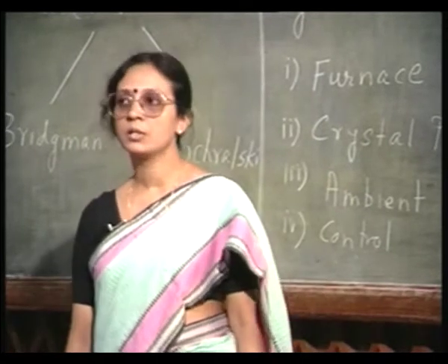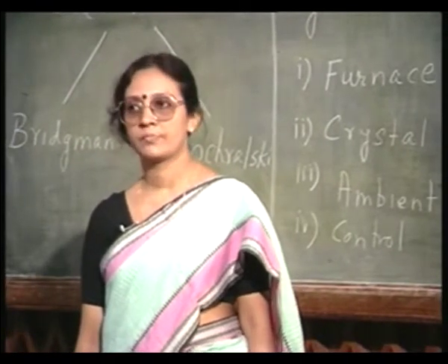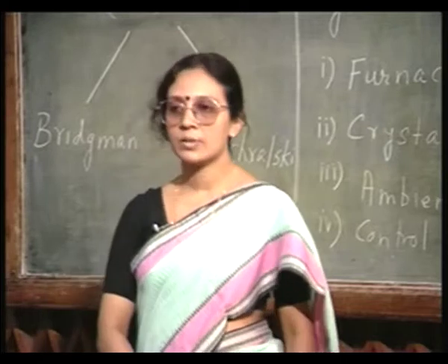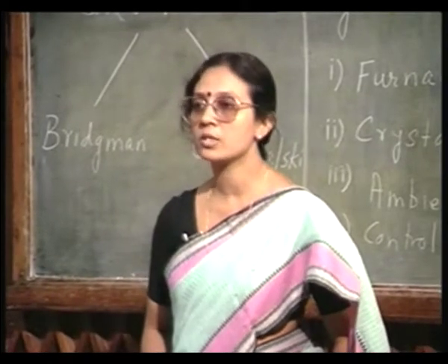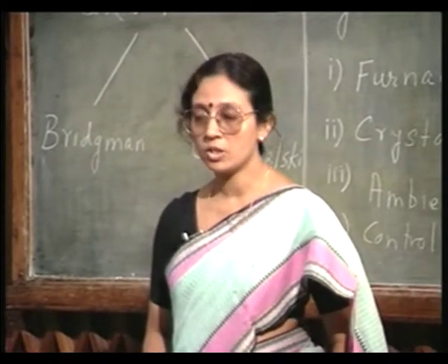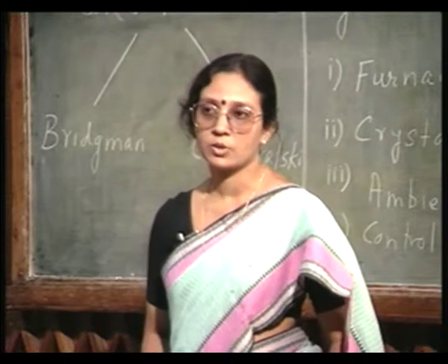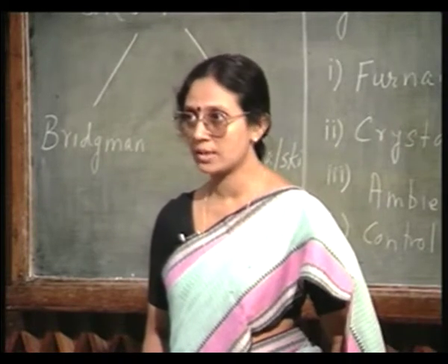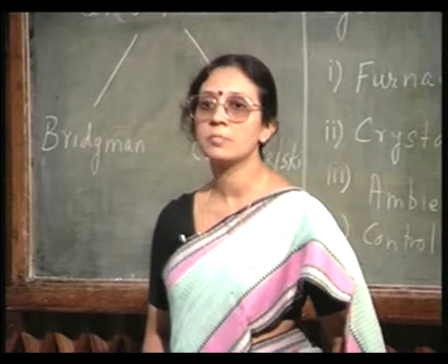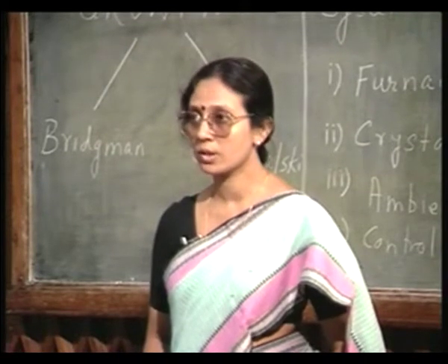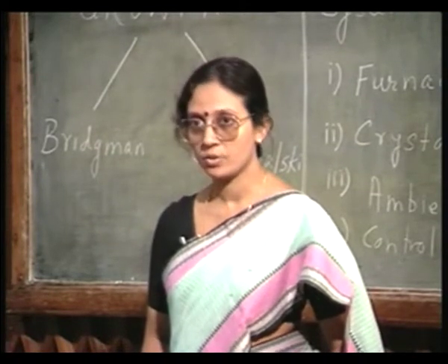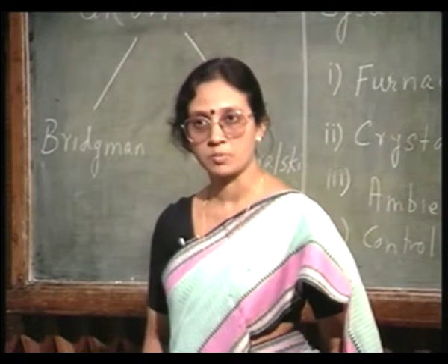Usually the crucible is made of quartz, and you can use it only once usually, because after the crystal growth, when you are cooling down the system, then because of the thermal mismatch, usually the quartz crucible is going to crack. So, you cannot reuse the crucible.